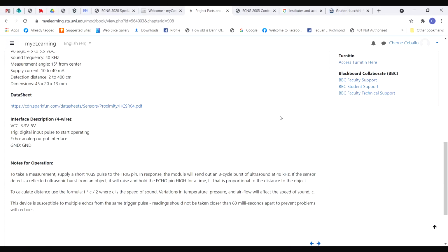All right. So now in my program, after I've sent the pulse, I'm going to, in some kind of loop, check the echo pin every time I loop around. And I could count up. It's up to me. I could count how long I was waiting on the echo pin, or I could just wait until it goes high, and then after it goes high, count how long before it goes low. You see how you could do that in your code?